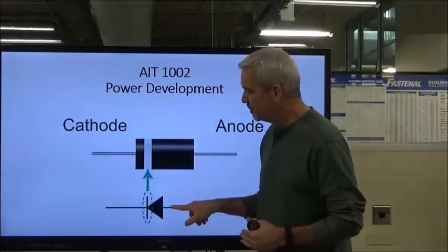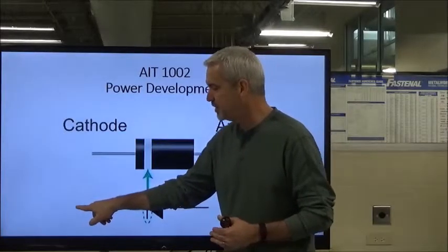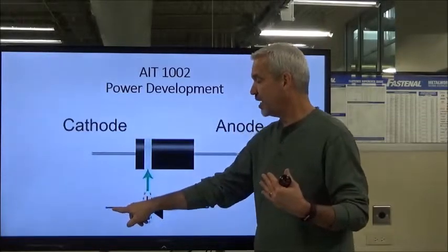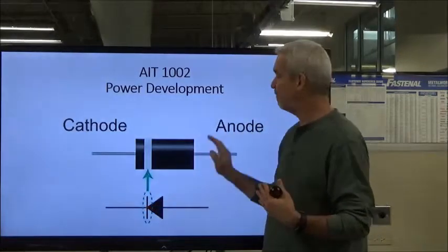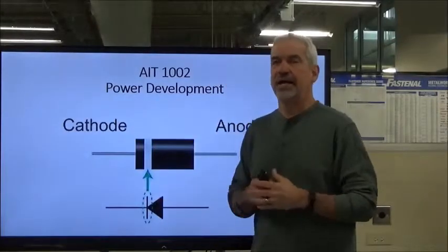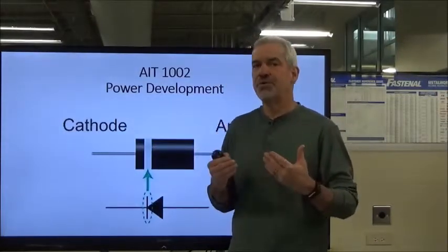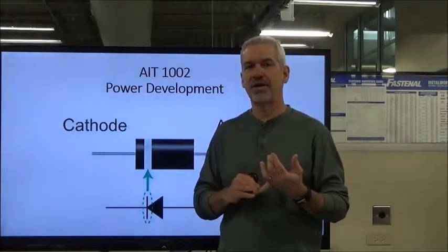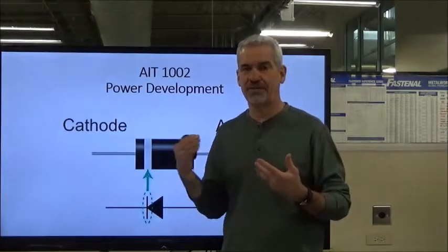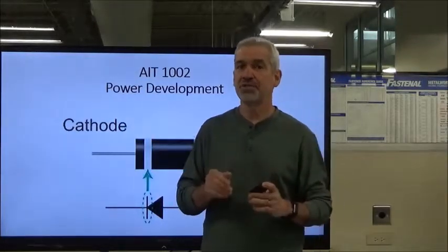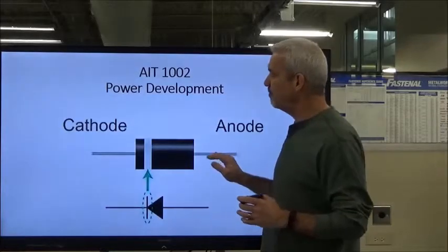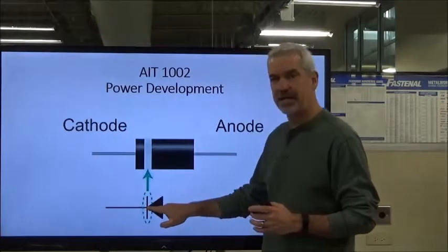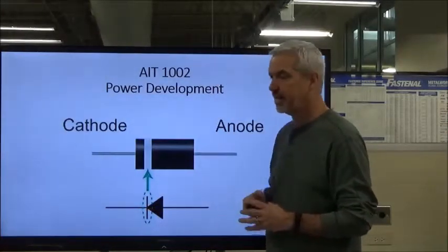We will allow voltage to go through the diode, and when it reaches its peak and reverses direction, again 60 times a second here in the United States, it tries to reverse, and it gets blocked right here. So we flow from anode to cathode. Now, in the textbook, you might see where it says you're flowing from cathode to anode. That depends on whether we're looking at electron theory or conventional theory of electron flow. We're going to be using conventional for this lecture, so we're going to be flowing from anode to cathode, from the big side of the triangle this way, but we can't come back through to the little side and try to go this way. That's where it's going to be blocked.